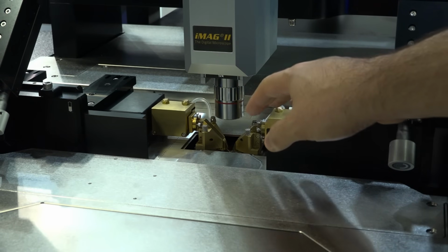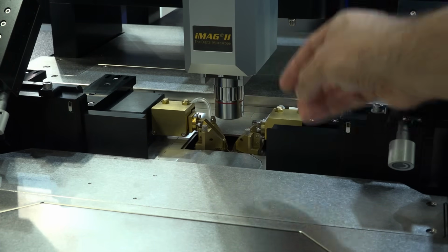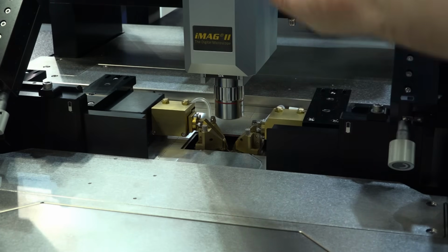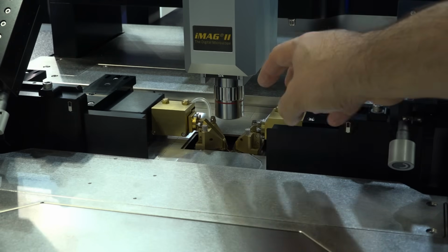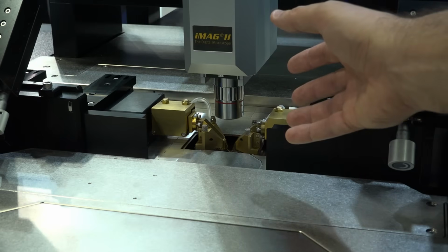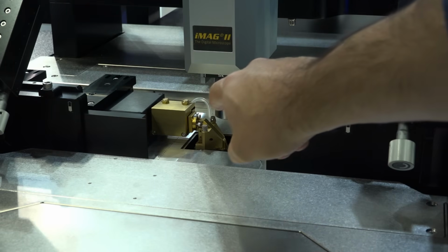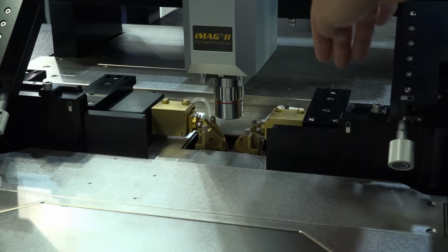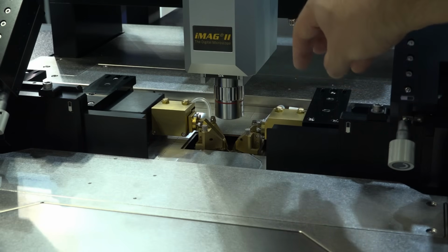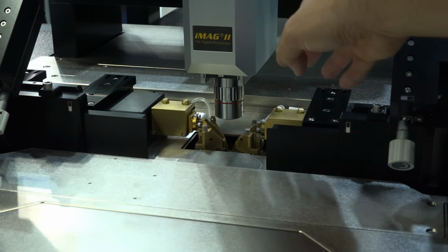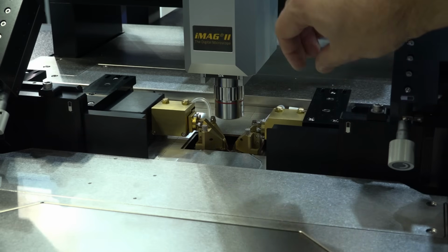We've seen this in the past, where they have this temperature barrier with laminar airflow that allows you to cool the chuck and heat the chuck without the heat coming up and without condensation appearing on the chuck. But the problem still remains that when you land your probes on the chuck that is at a certain temperature, whether high or low, you're connecting everything with a waveguide. So that temperature is going to go into the heads. These heads have been purposely brought in so close to the measurement to minimize any kind of interconnect. You don't want any S-bend, you don't want any losses in that interface, because that's all uncertainty as well. But when you bring things closer, of course you bring them thermally closer.